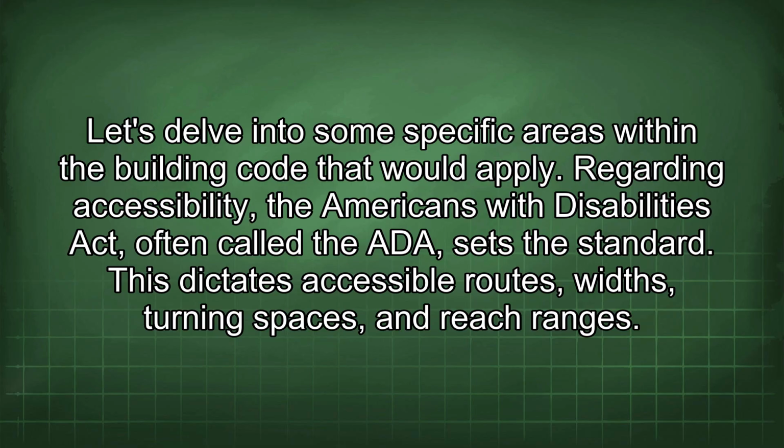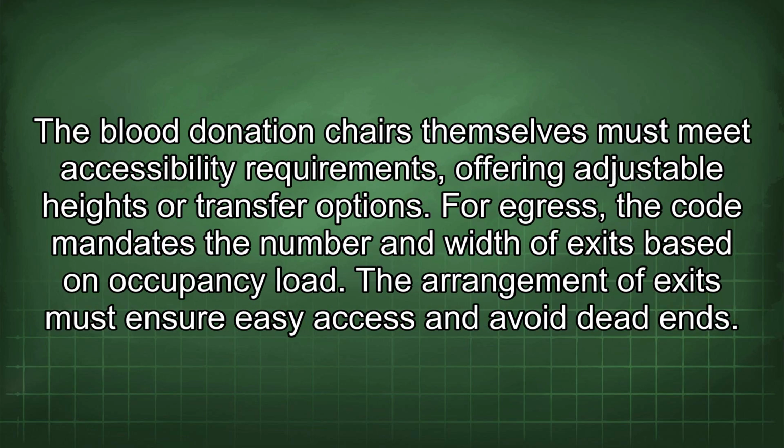Regarding accessibility, the Americans with Disabilities Act, often called the ADA, sets the standard. This dictates accessible routes, widths, turning spaces, and reach ranges. The blood donation chairs themselves must meet accessibility requirements, offering adjustable heights or transfer options. For egress, the code mandates the number and width of exits based on occupancy load. The arrangement of exits must ensure easy access and avoid dead ends.